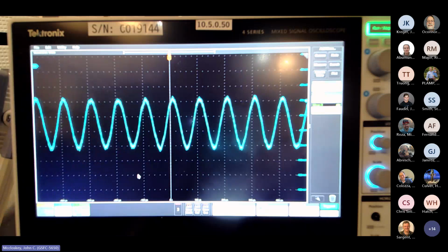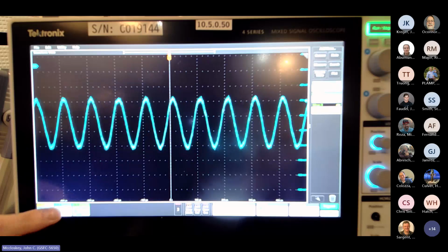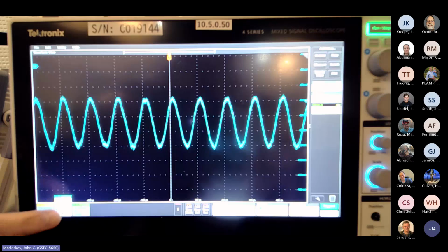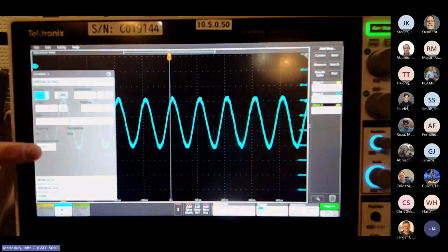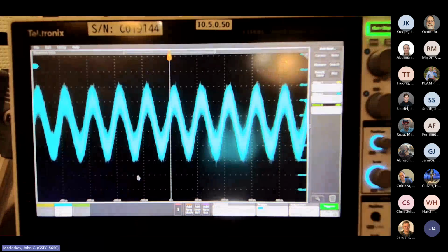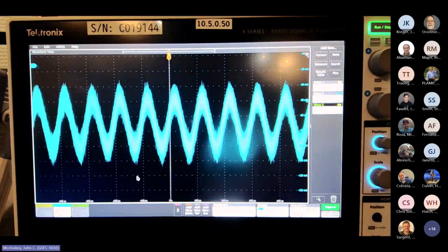I think a lot of it has to do with it being a fairly noisy probe. We're not terribly close to the noise floor, but we're getting a lot of excess noise through this current probe. But I'm just going to keep it on the full bandwidth because we're going up to 200 megahertz. Even the 250 megahertz bandwidth limit is something I'd rather not use.